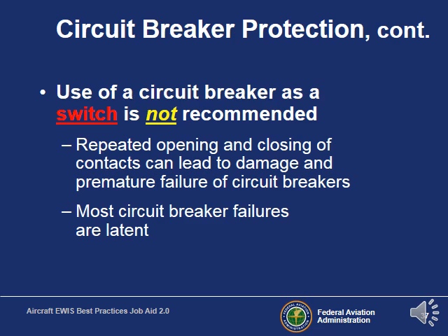Circuit breakers should not be used as a switch. Repeatedly opening and closing the contacts can cause damage to the circuit breaker, and then when we need the circuit breaker to function, later on it won't. Most circuit breaker failures are latent. That means that we don't know that they're broken until later, when it's really important. So please do not use circuit breakers repeatedly as a switch. They're not.